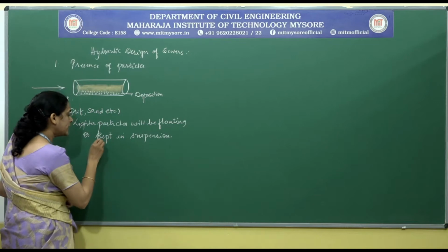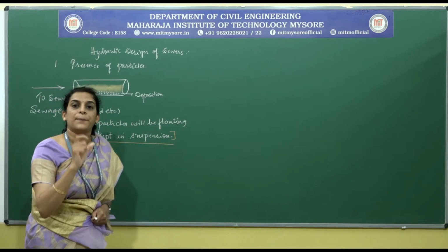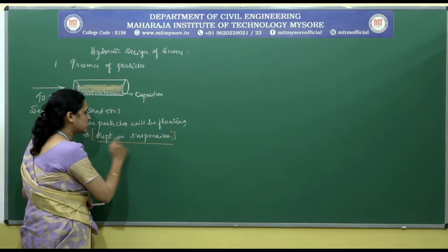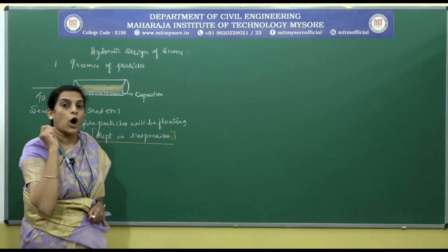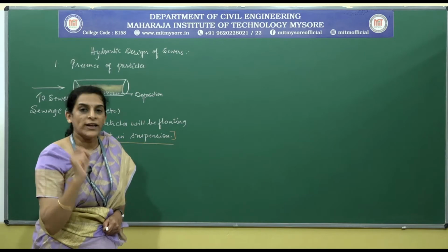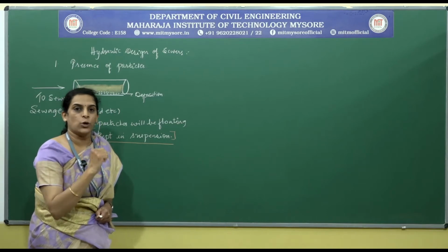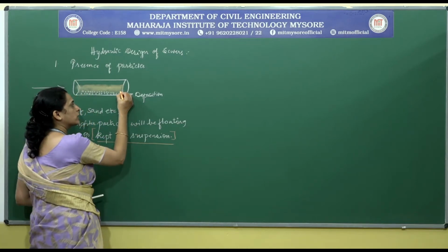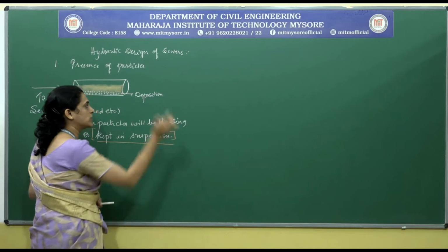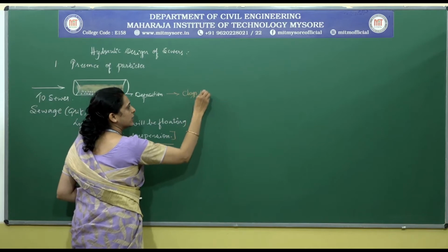Now I tell you this is very important. Lighter particles are kept in suspension. What is it that causes the suspension? All that we are supposed to know is about the velocity which keeps those lighter particles in suspension, which otherwise may make them prone to complete settlement, thereby causing deposition, which in turn clogs the sewer.